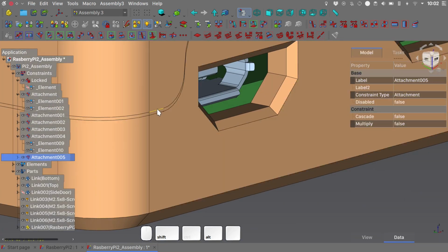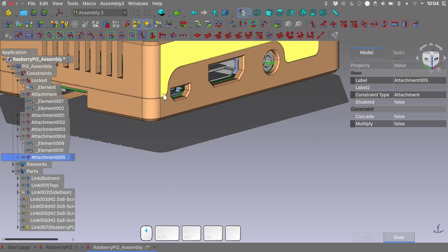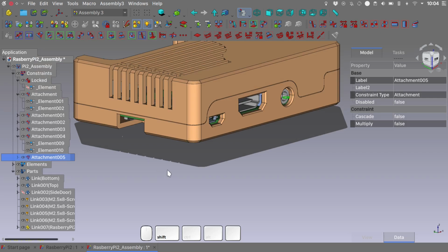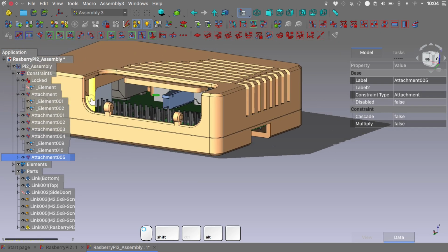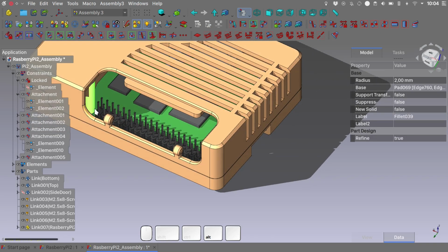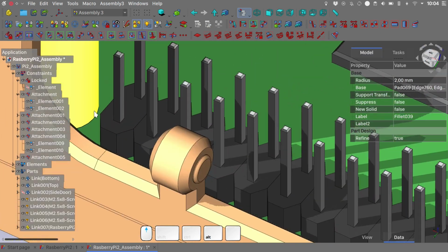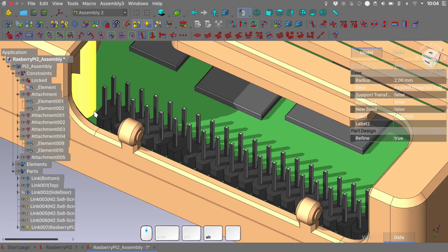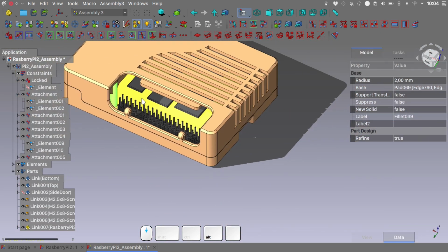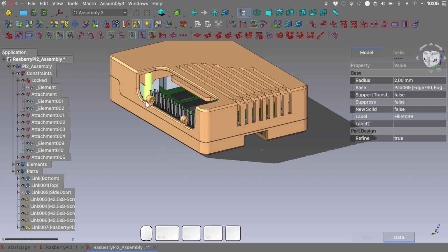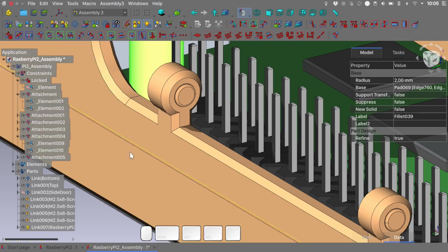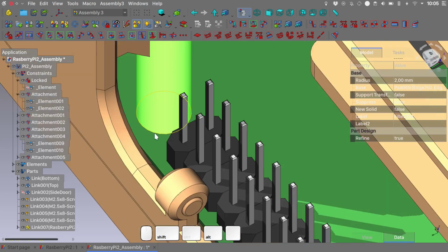This geometry is intersecting. If you followed the previous tutorials, you might remember that while constructing the geometry of the screw legs, this one here, we have given an offset of, if I remember correctly, 0.2 millimeters from the mainboard geometry. While doing the assembly, that offset will create this kind of mismatch, because it tries to mesh the geometry just like in real life.